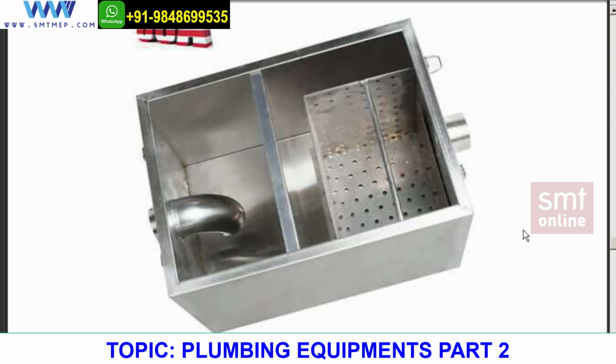And one more thing I would like to add over here: whenever we are sizing a grease trap, it should be vented with at least 30 to 60 centimeters. Vent, matlab, that should be having an air gap. Yes, an air gap, and in that air gap I'll be having one pipe inserted, that is called the vent pipe, so that the combustion or the gases should not form over there. It should be continuously vented.